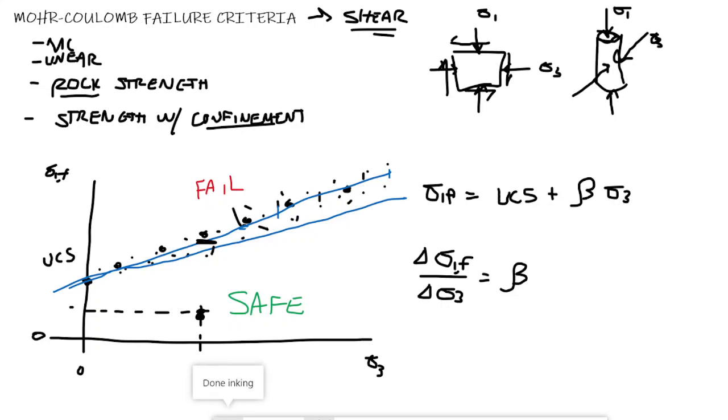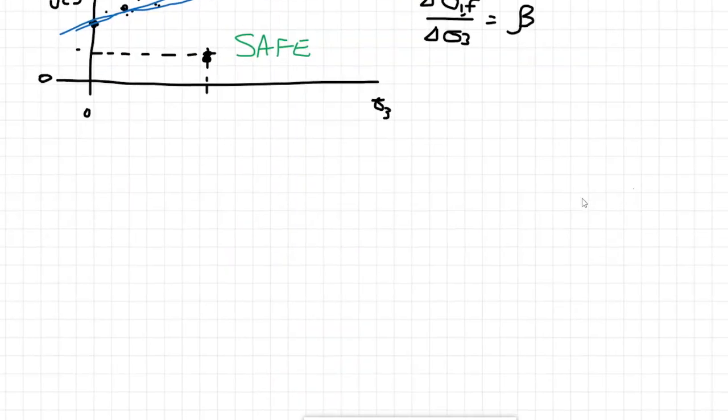Using that, we'll kind of launch pad into talking about the shear component, right? So we've gone from talking about the compressive stress failure envelope to a shear stress failure envelope. And to do that, we'll look at this guy again, and just as a reminder, remember we have a sigma 1 being applied straight down in that TCS, and then we'll also have our sigma 3. And remember, we have no shear stresses being applied in this laboratory setup, or very little in any case. And since there's no shear stress, we know that these are indeed principal stresses.